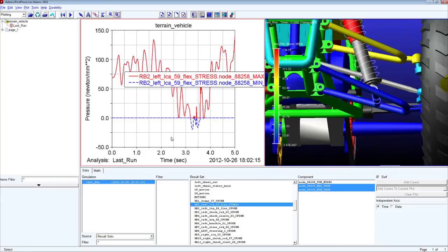as a fatigue criterion. So as a lookup stress value, we don't use a tensor, obviously, we use a scalar value, and we're using it to look up the SN curve. We'll be using the max principal when the maximum absolute value is higher than the mean principal, and vice versa. In this area here, you can see where the max principal is 0, the mean principal takes over. So the total excursion is from top of the max principal to the minimum of the lower principal.